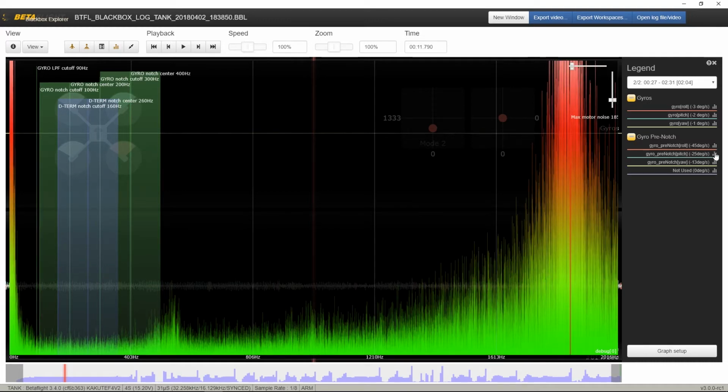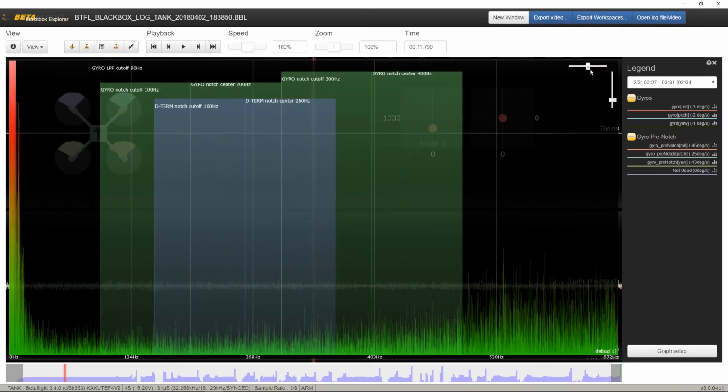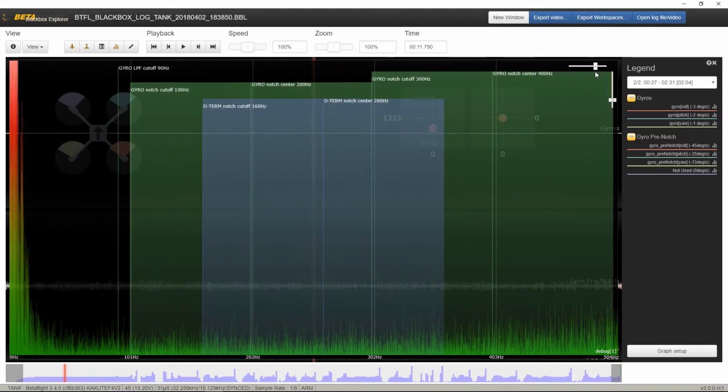So we check also the pitch axis. We can see that this noise spectrum is kinda different than on roll. The most prevalent motor noise is around 900 Hz. Also, this is not affected by dynamic filtering at all. This area for dynamic filtering is pretty clear already.